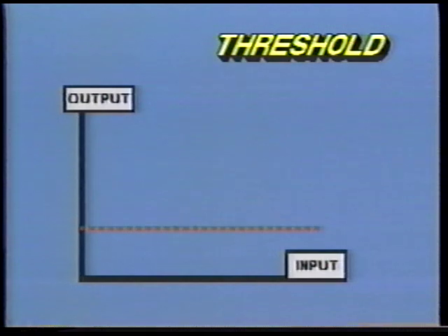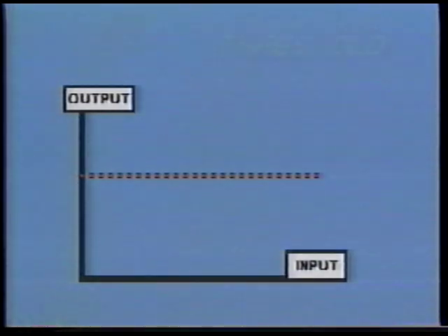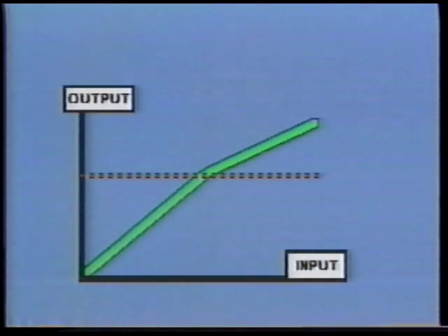In working with a compressor, you shape the sound envelope by adjusting several variables. The sensitivity of the device, the point at which gain reduction occurs, is controlled by adjusting the input or threshold control. When the input signal rises above the threshold, gain is reduced. The threshold pivot point on the input versus output curve is called the knee.